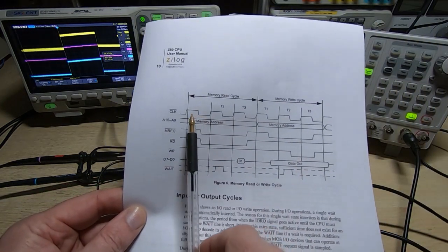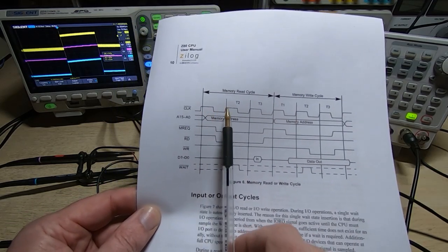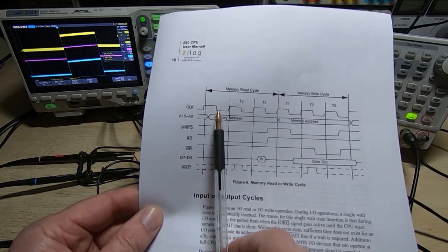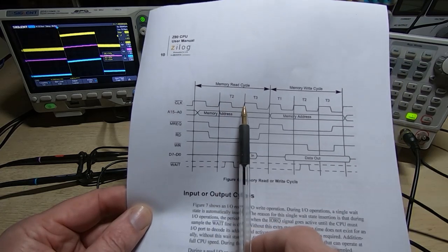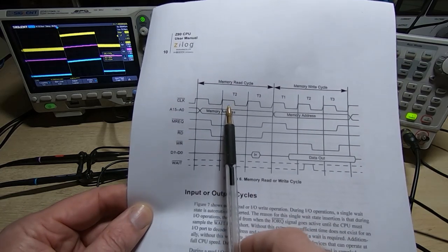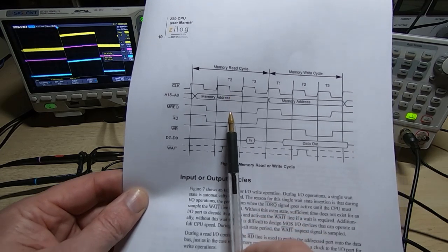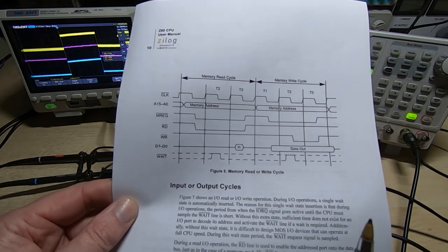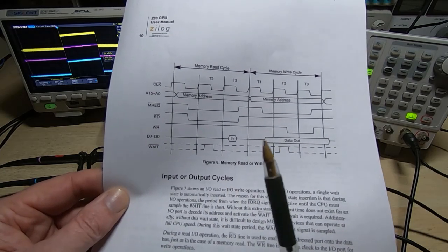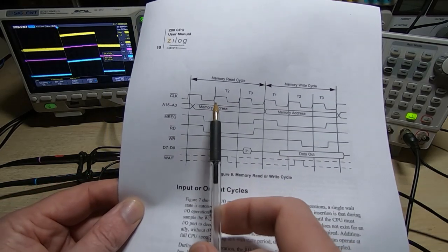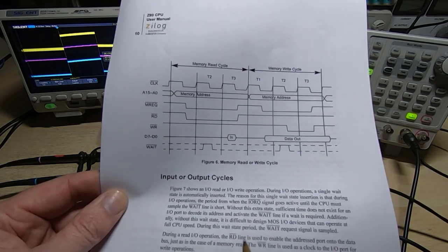So if we look at the clock cycles on the Z80 spec sheet, then if we're running the processor at 5 MHz, then of course each of the clock periods is 200 nanoseconds, but the half cycle time is of course only 100 nanoseconds. So a lot of the time we only have 100 nanoseconds to carry out an entire part of the process. If it's decoding something or switching a multiplexer or something of that nature, then the events have to be completed within a certain length of time.